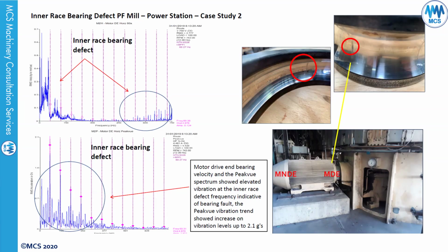Once this is done, you start to view the bearing faults, and they will match those non-synchronous peaks. When they match, you will be sure that this non-synchronous peak, matching one of the bearing faults, is a bearing defect. As you can see here, we see this non-harmonic component with a few harmonics, and when we line it up with the inner race bearing defect frequency, it matches. When we look at the time waveform spectrum, you will also see the non-synchronous peaks with harmonics and sidebands at the running speed, and this was a good indication of a bearing fault.